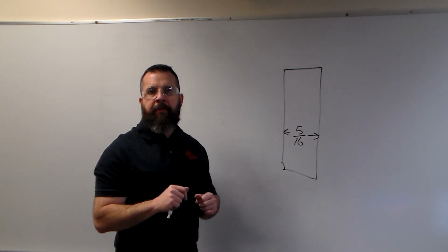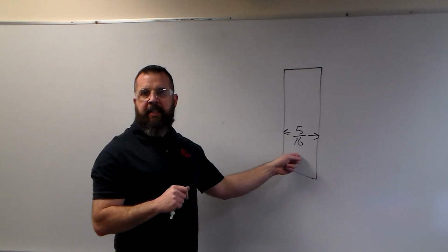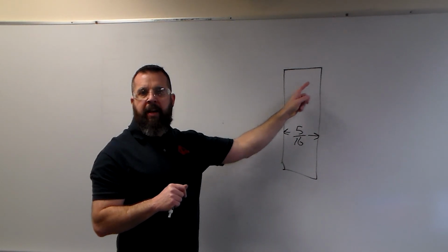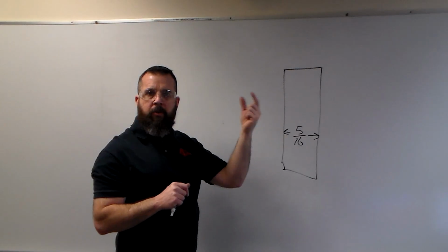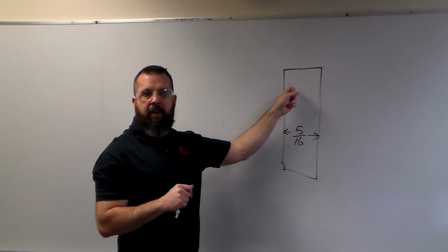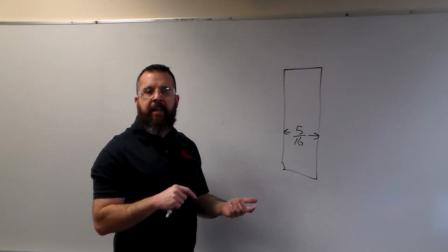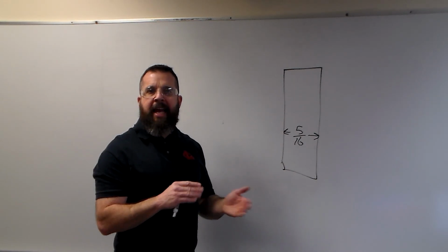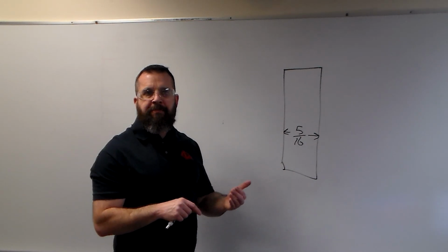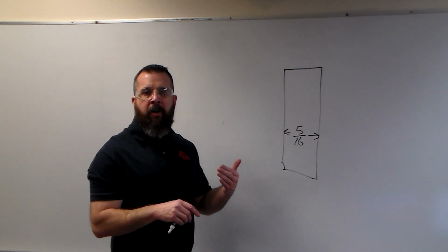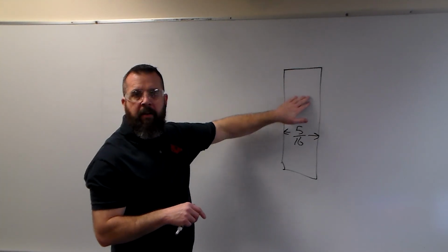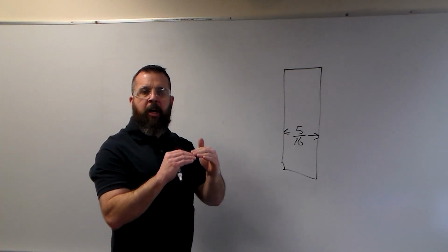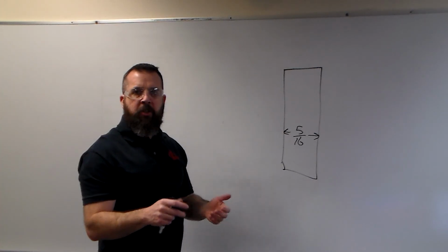We're going to start with the 3/16 wide grooving tool because if we make a mistake, it can become the 1/8 inch wide tool. Now, if this is 5/16 and I'm going to grind a 3/16 wide grooving radius on this end of the tool, I would need to subtract 3/16 from my 5/16, and that would give me 1/8 of an inch that I'm going to be grinding off the part. So you'll put bluing on this surface, and then you'll set the part on the height gauge, and you'll come up 1/8 of an inch, and you'll scribe a line.